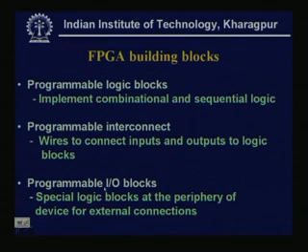Now, programmable IO blocks: special logic blocks at the periphery of the device for external connections. So, not only the logic blocks and the interconnection blocks are programmable, but the IO blocks as well, that means which input we want to feed and which output we want to take from the design is also programmable. So, these are the three programmable blocks, the basic building blocks of FPGA.